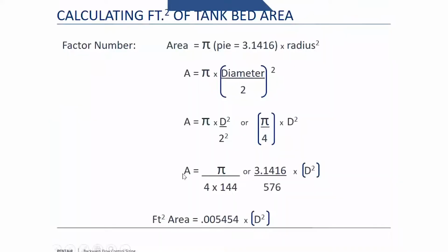Unfortunately, it's math time. One of the first things we need to understand when we are talking about carbon filtration, especially in relation to Fleck and Autotrol valves on structural tanks, is tank size. We have to start with that surface area. That acts as our initial contact plane of water meeting carbon. And then it's the column that we're defining below that. For most applications of activated carbon, we're going to have a 30 to 36 inch carbon bed, period. It can get bigger, longer than that, but typically it's not shorter than that.